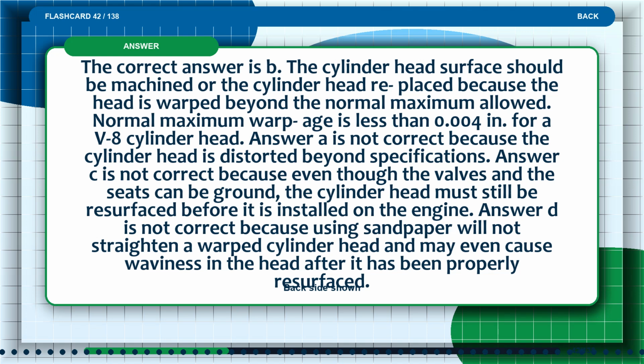The correct answer is B. The cylinder head surface should be machined or the cylinder head replaced because the head is warped beyond the normal maximum allowed. Normal maximum warpage is less than 0.004 inches for a V8 cylinder head.